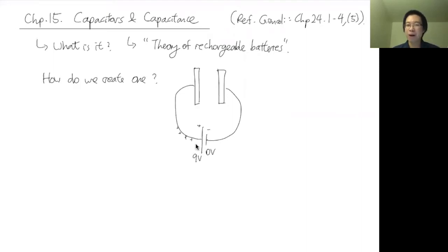So they try to go from the positive, high potential to low potential, right? So this looks like a promising path. So they'll start to go. Remember also, if this is an ideal conductor, ideal wire with 0 resistance, then the potential here and the potential here, when I say potential, I don't mean difference, I mean absolute potential, is the same, right? So this is also 0 volts. So according to this guy, this positive charge, this looks very attractive. Pun intended there, it looks very appealing and it would like to go to a lower potential. So it moves all the way to here and it'll keep moving.